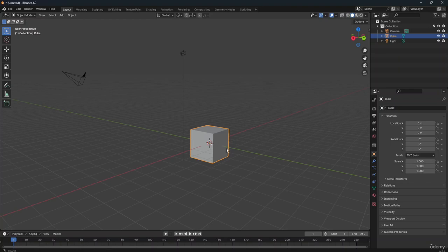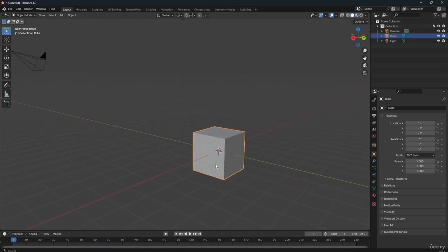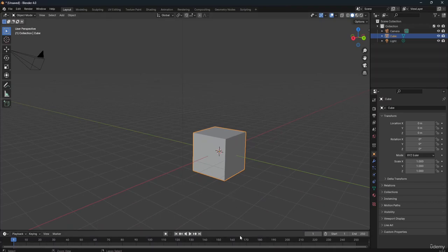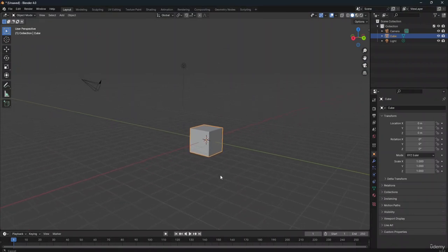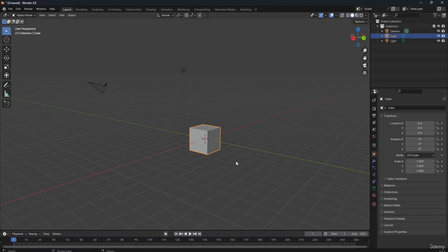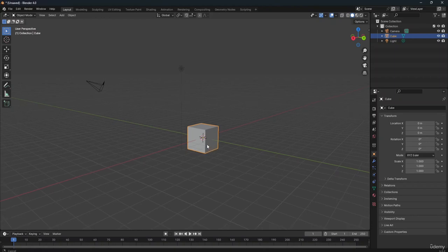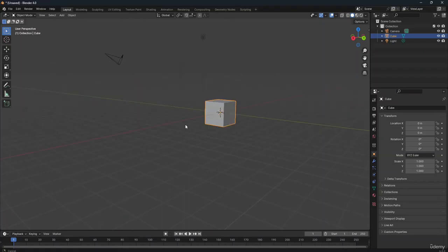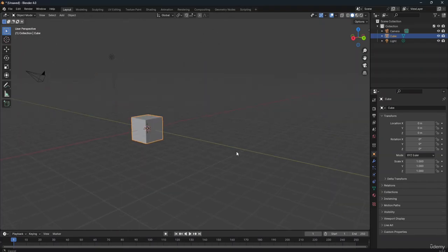Okay, so if I hold shift, and now hold control, and click the minus button, here you can see I can zoom in and zoom out. Let's say I will zoom out more as well. Let's hold control and click over here, and I will zoom out from here as well. And the same way, if I hold shift and want to move the perspective, I can move the perspective from here as well. Okay, so this was about if you don't have a mouse with you.